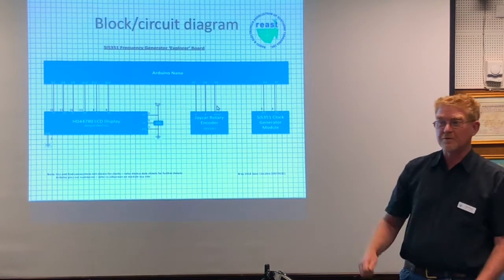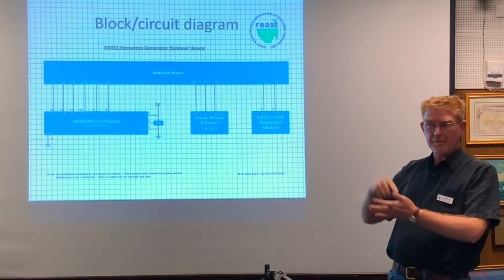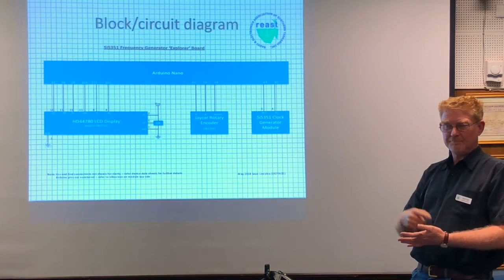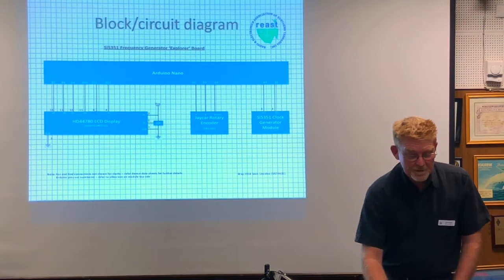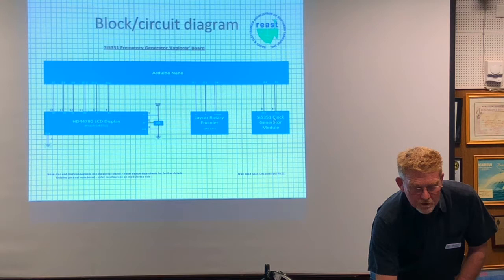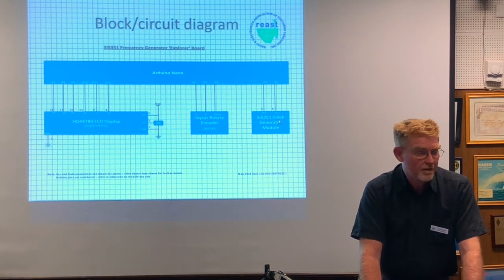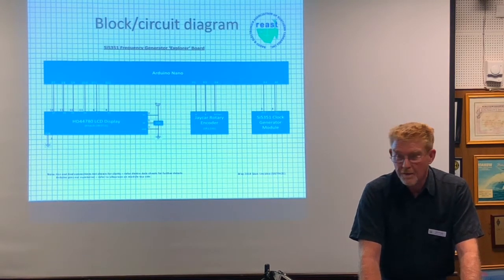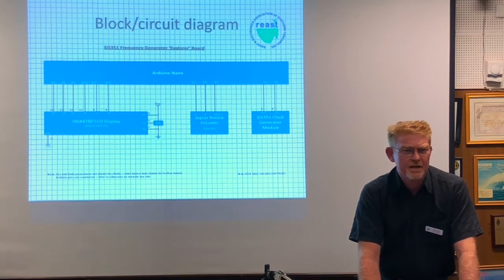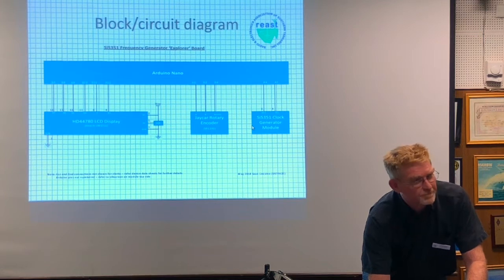The idea of the rotary control, you've got a quadrature encoder, so you can work out how many steps in either direction, and a button you can press to indicate you're doing something clever. There'll be something clever later, just to get it working first. And like I said before, just those 2 pins to talk to the clock module. The clock module itself has 3 clock outputs. I'm just using one of them for this particular show and tell. There are versions that will do, I think, up to either 8 or 20 independent frequencies coming out. Is that using I2C? Correct. Okay.